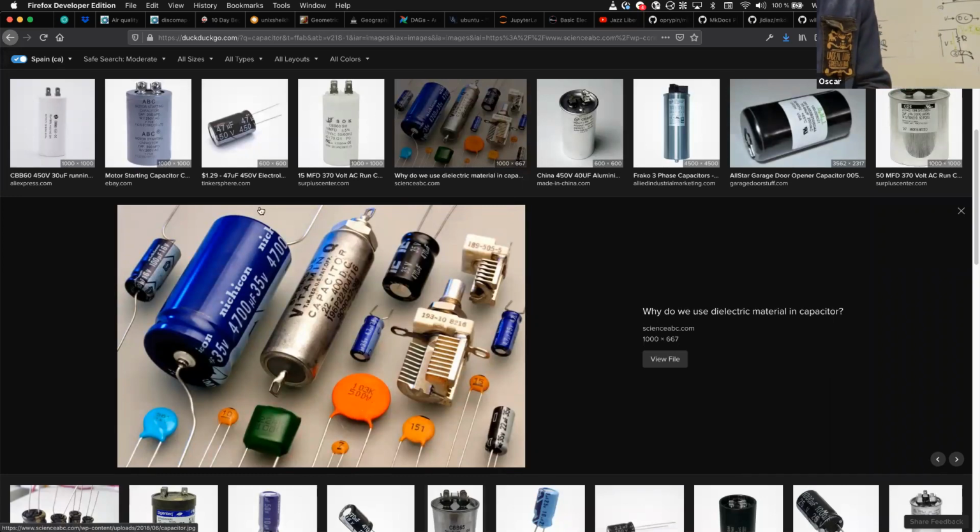The other ones that look like batteries, more or less, are called electrolytic capacitors, and they have polarity. Very importantly, one of the sides is the negative and the other one is the positive, and it is marked on the capacitor itself with a small white band that has a minus drawn on it. It's a convention, so the negative side is very clearly marked. Why is it marked? Because it can explode. Like batteries? Those are not batteries, they are capacitors. They operate somewhat like old acid batteries, but they don't have the same principle.